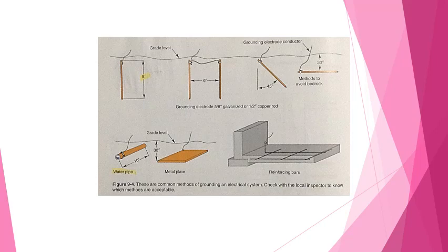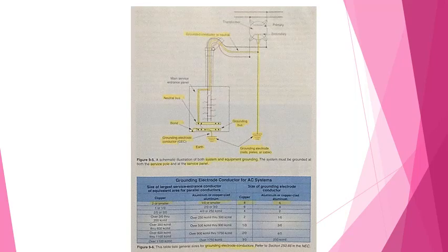The grounding of the neutral wire is done at both the building's service panel and at the power supply pole. For this, see figure 9. A commonly accepted method of system grounding is to connect the neutral conductor to one or more ground rods. The rods must be driven to a depth of at least 8 feet. The depth is important as the rods must be in contact with moist earth for good grounding.